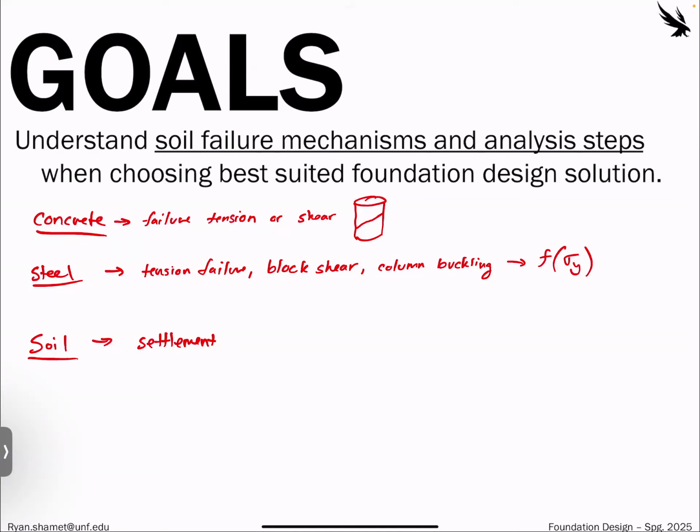You'd never notice it walking in, but there was one door with an ADA step down, and since you had to build that up, the door was just low. You had to kind of step in a little bit. It used to be a normal-sized door, but the whole thing settled about 3 inches, so you had to be careful walking into it. So accessibility is fine. Is that deeming a failure? In that case, no, but we could have a case where settlement is an issue.